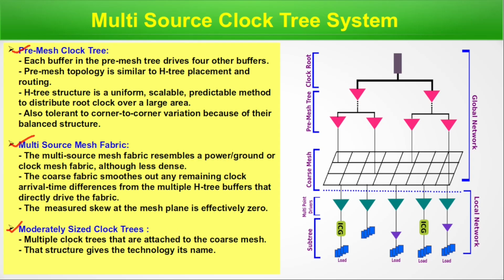And now finally, moderately sized clock trees. Multiple clock trees are attached to the coarse mesh. That structure gives the technology its name, multi-source clock tree system. It's a local network, multi-point drivers are there, integrated clock gating is done here, and this is the subtree. After mesh, there is a subtree, so the name comes from this structure.